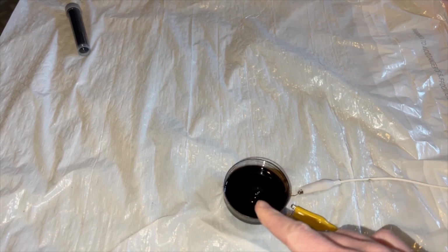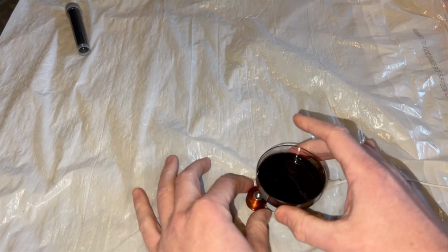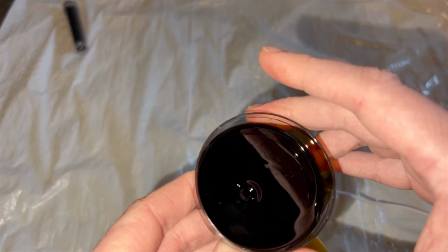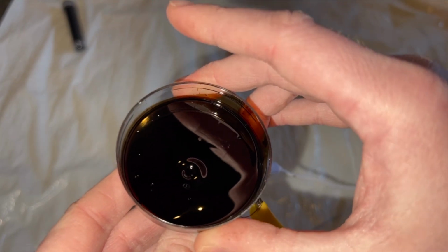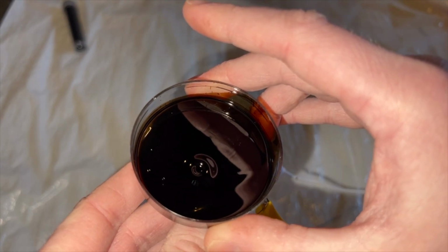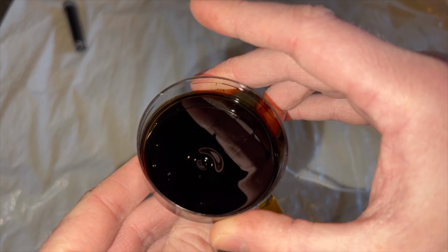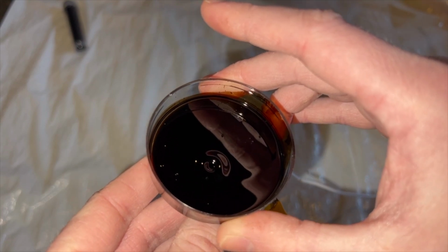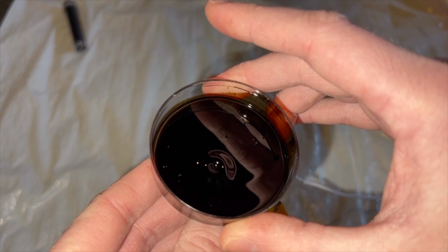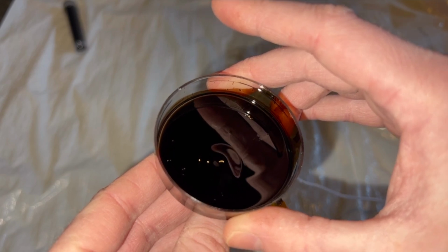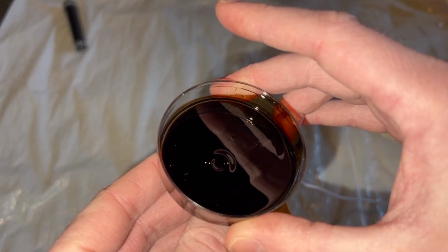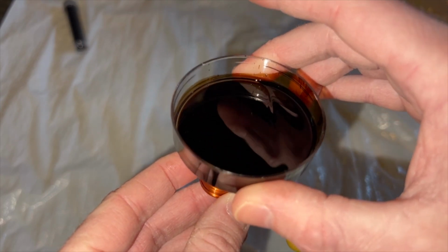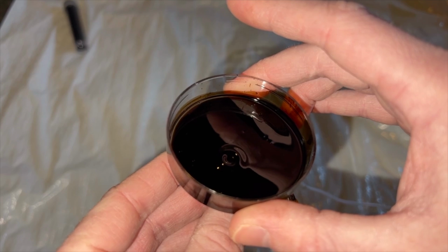If you see it right here, I'll bring it up to the camera, you can see that the electromagnet does in fact create a field, and as you pull it away from the camera or from the petri dish, it will weaken and then go away completely. And in a real dynamic suspension system, this electric charge will be changing thousands of times per second to adjust for the road conditions the vehicle is experiencing.